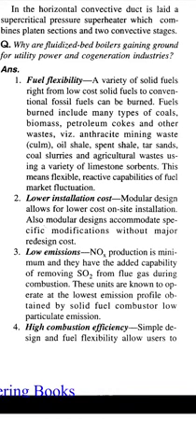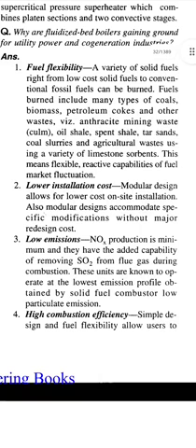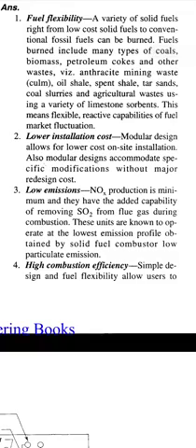Second, low installation cost. Modular design allows for lower cost on-site installation. Also, modular designs accommodate specific modifications without major redesign cost. Third one is low emission. NOx pollution is minimum and they have the added capability of removing SO2 from the flue gas during combustion. These units are known to operate at the lowest emission profile obtained by a solid fuel combustor, with low particulate emission.